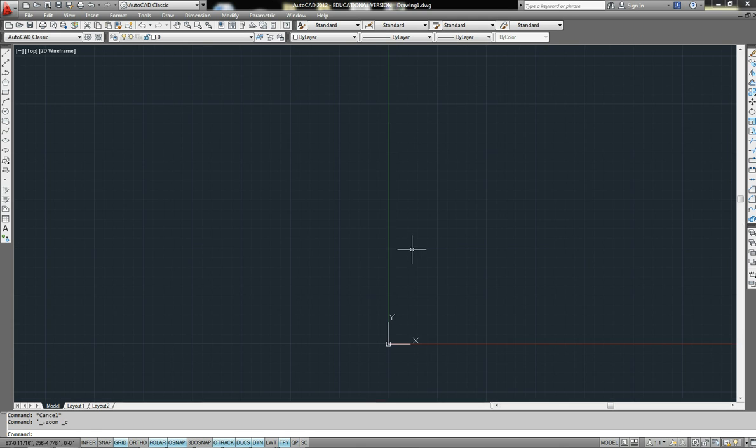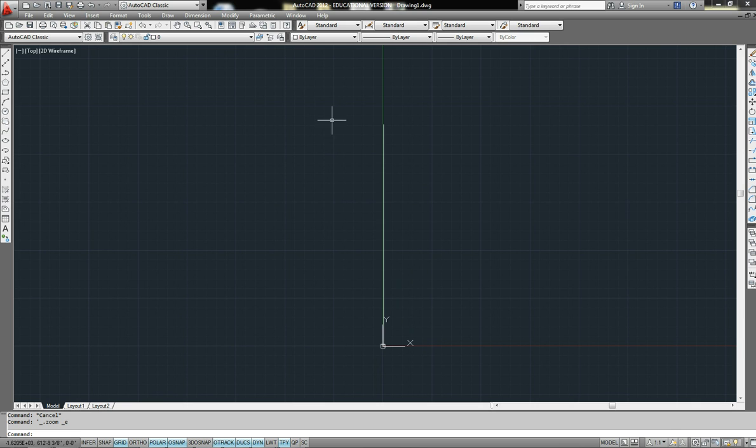So again, to clarify how this works, if you want to draw a line from any point to any point, you could do it two ways. You can select the start point, and then click somewhere to select the end point, or if you want a specific dimension, click the line command. Again, click where you want to start, and drag in the direction you want to go.